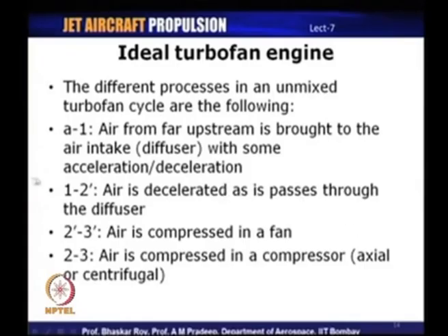We have the diffusion taking place between stations A and 2 prime, and then we have compression in the fan between 2 prime to 3 prime, and compression in the compressor, which could be axial or centrifugal, between stations 2 and 3. So, 2 to 3 is compression in the compressor.